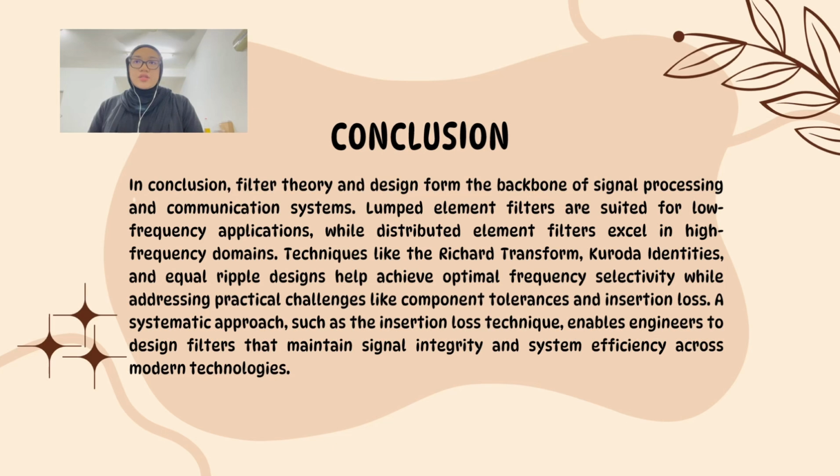Techniques like the Richards transform, Kuroda identities, and equal-ripple designs help achieve optimal frequency selectivity while addressing practical challenges like component tolerances and insertion loss. A systematic approach, such as the insertion loss technique, enables engineers to design filters that maintain signal integrity and system efficiency across modern technologies.